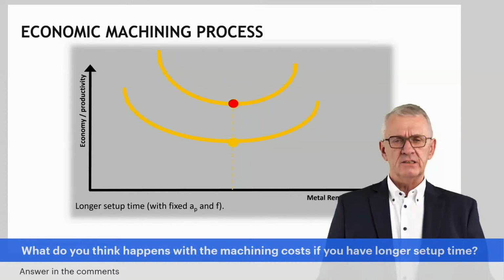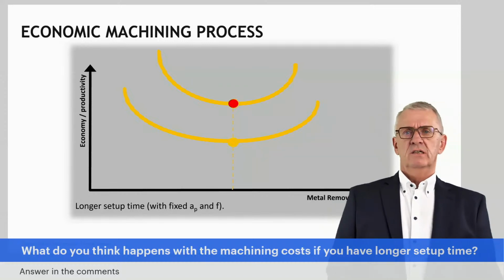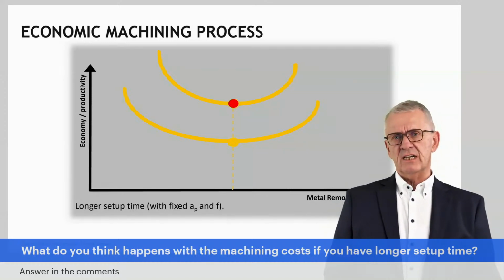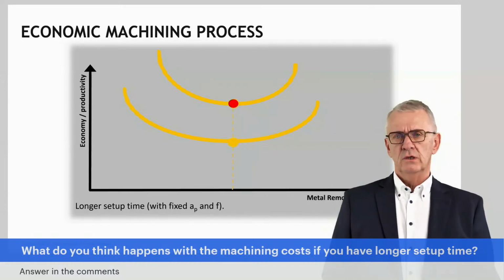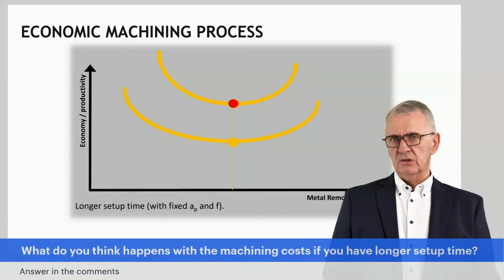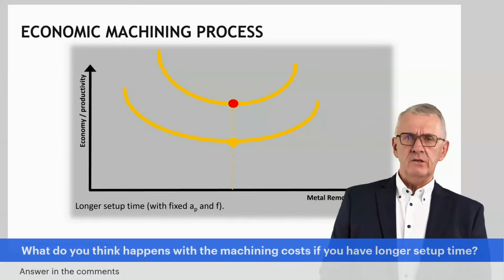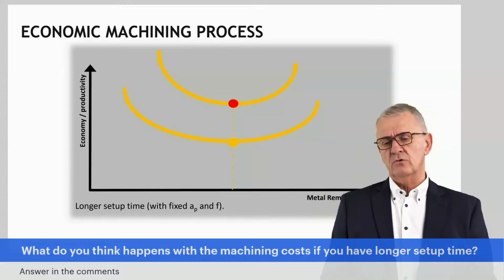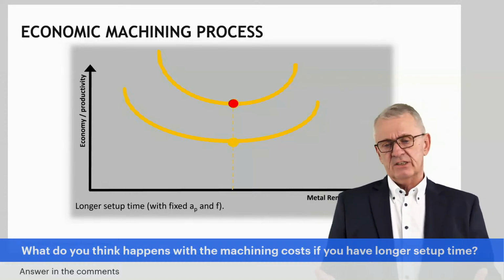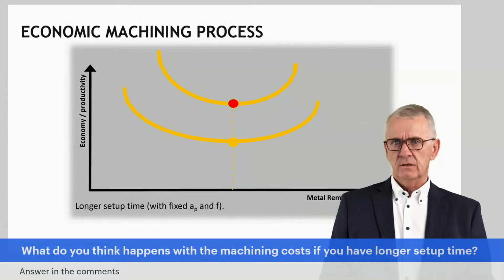And the intriguing thing is, and this is something you should be very much aware of as a machinist, in how you select your cutting conditions afterwards, there is nothing you can do. Increasing cutting conditions would make things worse. Reducing cutting conditions would make things also worse. All the time you spend on setup, it was on the tip of my tongue to say you lose in setup, but yeah, setup is needed, but let's say what you spend on setup is costs which you cannot recuperate during the actual machining.